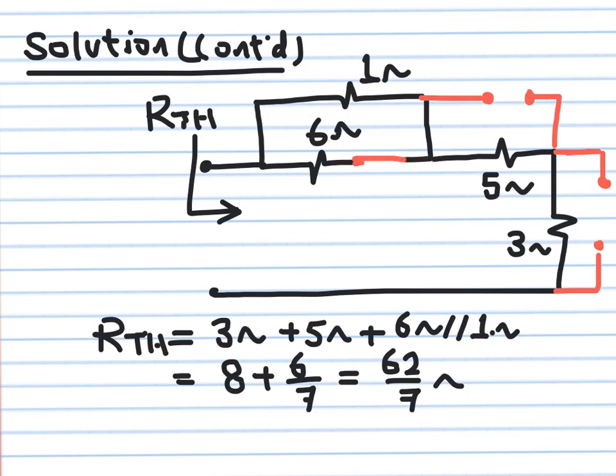So now the circuit does not have any independent sources. Okay, so effectively, this is how the model looks like. And the model now, if you try to see it, this is how it looks like now. Okay, so I have now just R Thevenin, and there is no V Thevenin because V Thevenin now is 0. Because V Thevenin, as we agreed, represents all your sources. So looking into this circuit here, you must see R Thevenin, and this is what we have here. This is now our circuit after we removed all the independent sources.